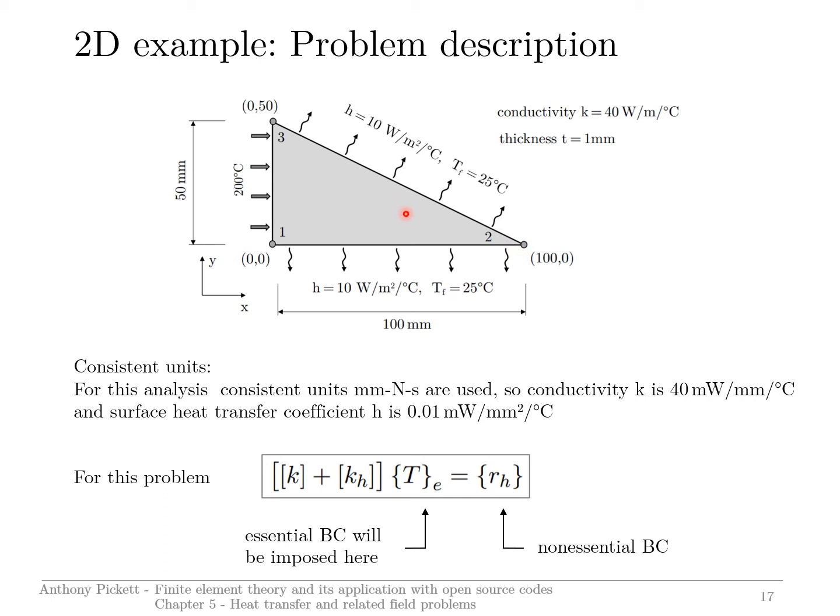Each point within this material would slowly heat up. There would be this internal storage taking place. And this was shown to depend upon the density of the material and the capacitance. This was a term that we had in the governing equations.